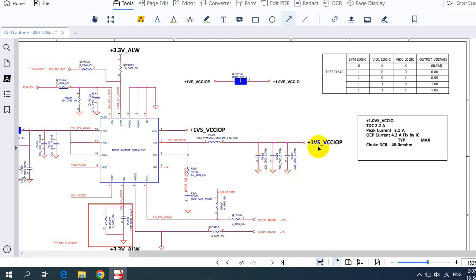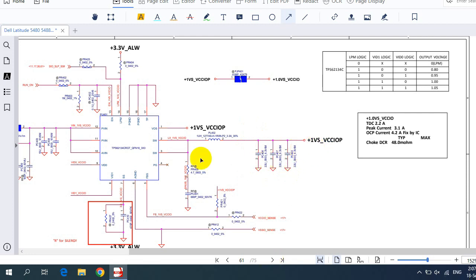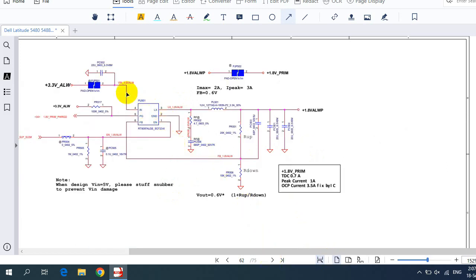Okay, we will get this voltage, but for the complete, entire circuit, we find here MOSFETs, inductor, and current sense resistor and electrolytic capacitors in order to filter the current. So here is the same working principle. We have just 3.3 volts. So this is another reason why we don't have MOSFETs, electrolytic capacitors and current sense resistor here, because we have just 3.3 volt as input voltage.